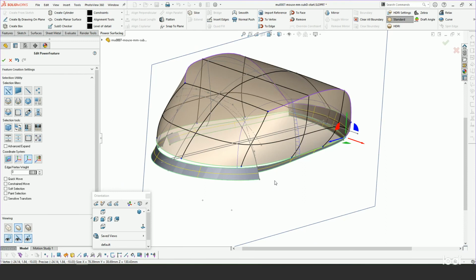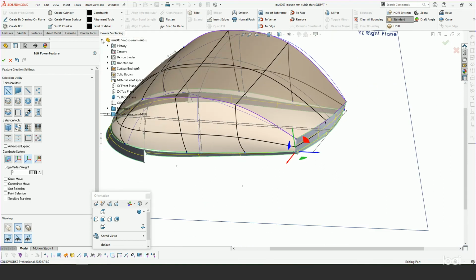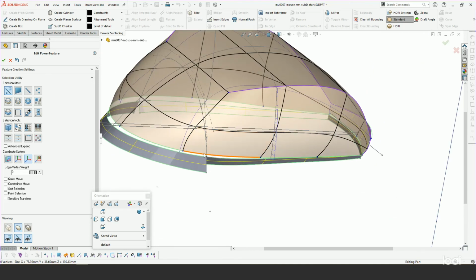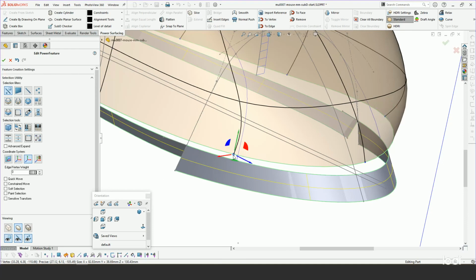So now we have the perimeter where the chamfer is, and let me just hide that one surface in front, so we're not going to get confused between the two. So this upper part, I'm just going to click on this and say hide for the time being. And we're going to align the Sub-D edges to this SolidWorks geometry, and it will stay aligned. Also, if this SolidWorks geometry updates, the Sub-D will update on top of it.